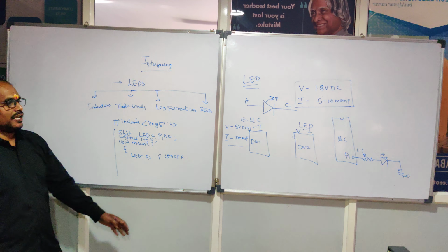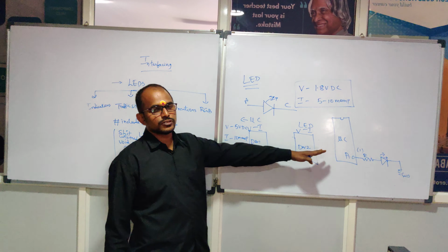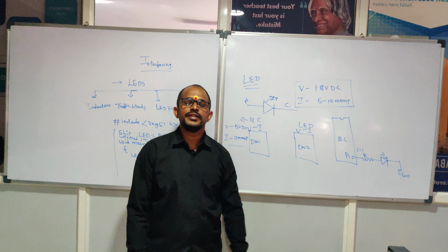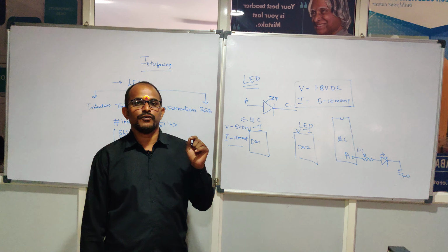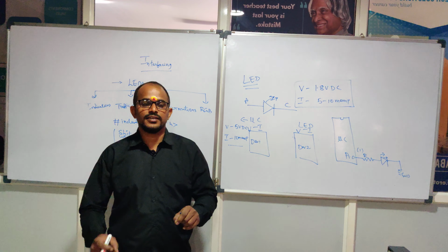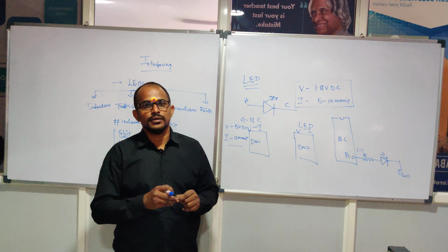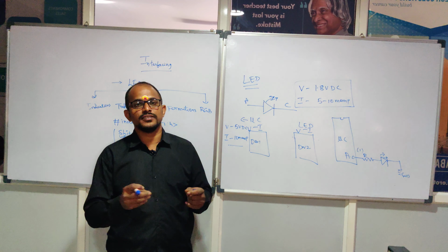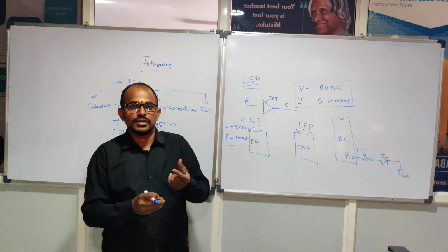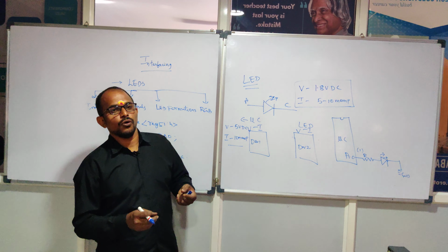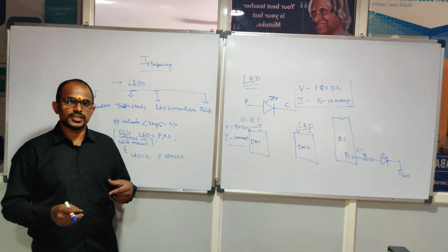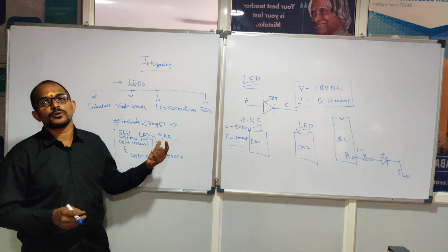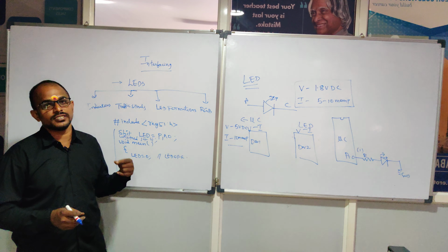because the external peripherals you connect to the microcontroller need some time to respond. Even if I am giving supply to the LED, it doesn't turn on directly. If I remove the supply across the LED, it doesn't go off directly, because it has its own response time. Peripherals always have their own response time, so you need to provide time delays in between logic changes.